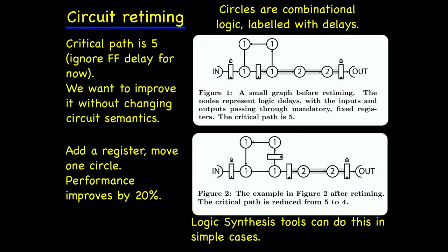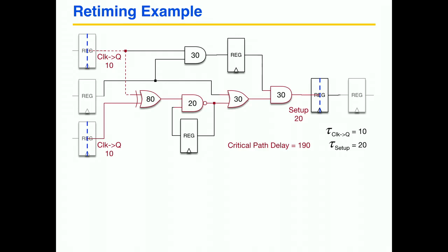Right. And that's the idea behind register retiming. The logic synthesis tools will try to do this for you in simple cases, right? But there's many cases that it won't do that. So it's best to think about this in your own designs for yourself, and don't just leave it to the tools. Let me give you another example, a slightly more complicated example.